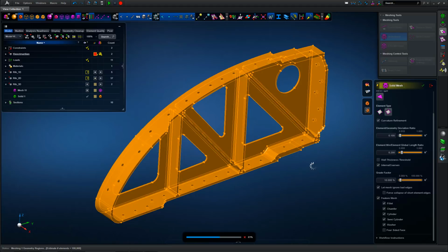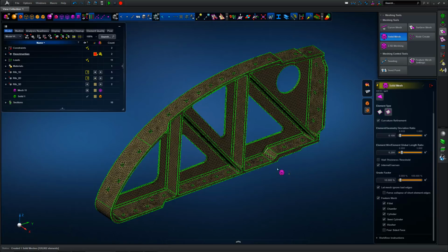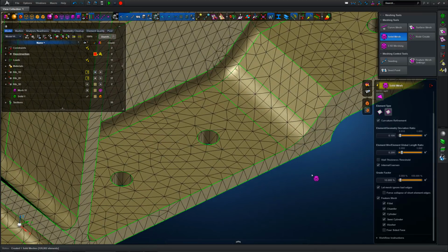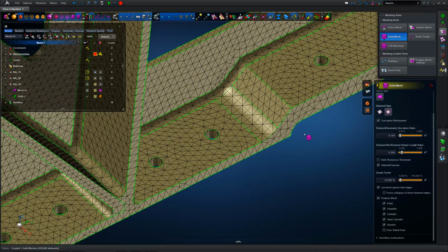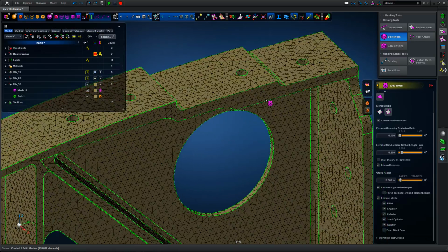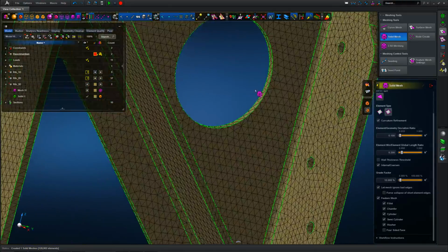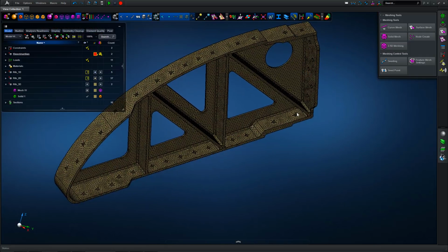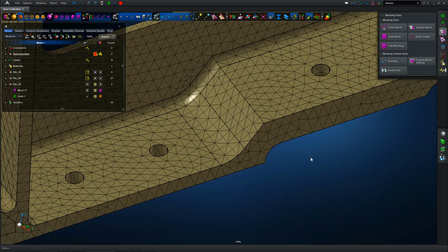as an example, and also the fillets in this joggled feature within the rib where we have double curvature in terms of the fillet definition, which may be an issue in terms of crack propagation. And again, you can see we've got a ring of elements around the fastener, and we've got good control over the fillet features in that particular region. Around the lightning hole we don't have a ring of elements, but we're not particularly concerned about that, given how we've controlled the feature mesh settings for the overall rib mesh definition.